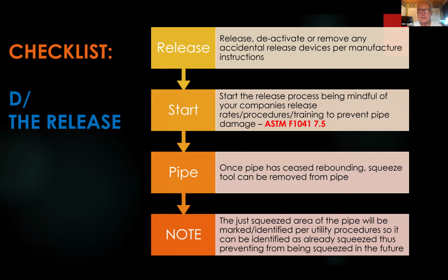Again, we've taken that from round to flat, and then we want to go back again. So those molecules have had a big workout, if you will. They've run a big race. We want to make sure that the pipe stays intact, so we're not damaging it. If we go too fast, then we are damaging it. They could crack at that point. That's why that rate is so important, that ½ inch a minute. Take your time. So that release rate really is more important than the squeeze rate. Oh yeah, for sure. We've changed the whole shape of that pipe, right? So we want to make sure we follow that, and we're not in a hurry to go home in the afternoon. We want to make sure we get it done properly.